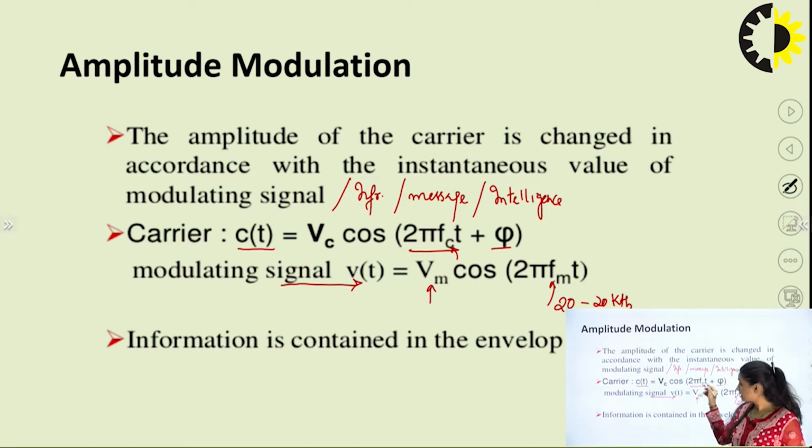Whereas the carrier, we know in most radio wave communication, has a frequency varying from megahertz to gigahertz range. So the frequency shifting that will be followed is from hertz and kilohertz to megahertz and gigahertz. The actual message signal will be in the range of hertz and kilohertz, and it will be shifted to megahertz and gigahertz, that is the frequency of my carrier wave.